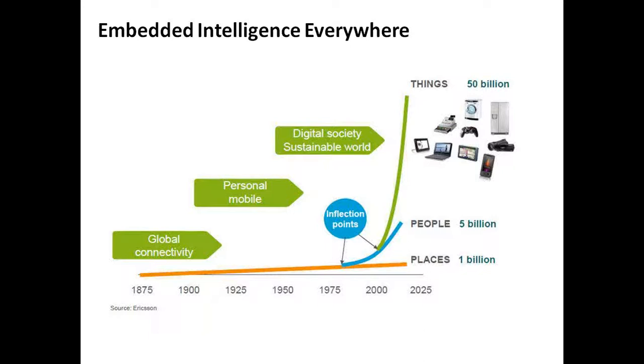And from that perspective, Zigbee scores very high, and there are a few other technologies like RFID and ANT networks or dust networks that are also very comparable or even sometimes superior to the Zigbee network itself. And next comes Bluetooth. It's lower, maybe the battery life may be like 10 days if it keeps operating. Wi-Fi is even lower in terms of battery life, but mostly Wi-Fi is today used for powered connections. And cellular, we all know it's about a week or so of battery life.